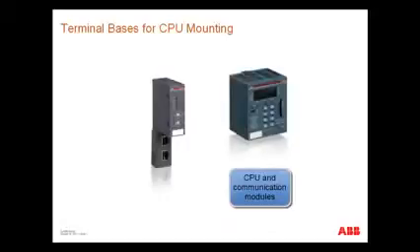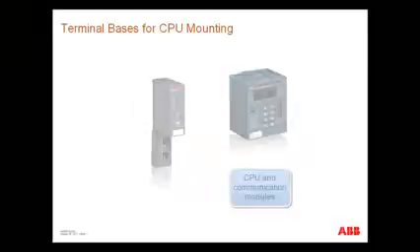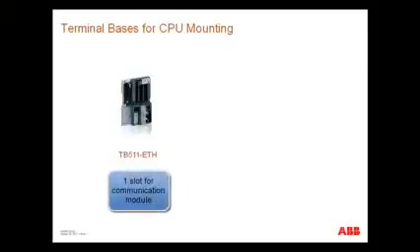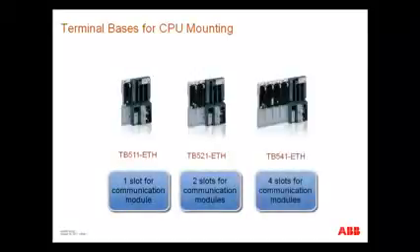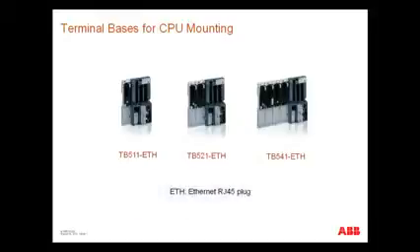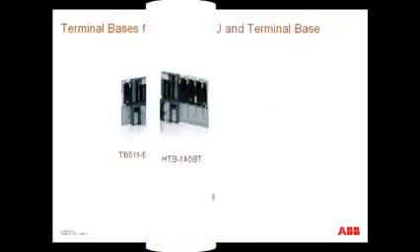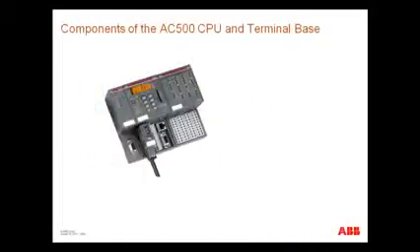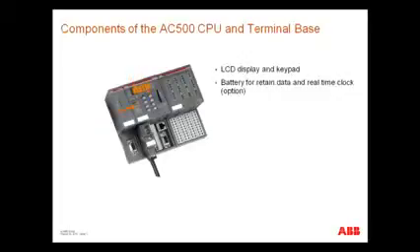Modular controllers and communication modules are mounted on a terminal base. Terminal bases with 1, 2 or 4 slots for communication modules are available. If you don't need any, use a module TA524 for covering the slot. The controller is equipped with the following components: LCD display and keypad, battery for backup of retained data, and a real-time clock. SD card as external memory device.